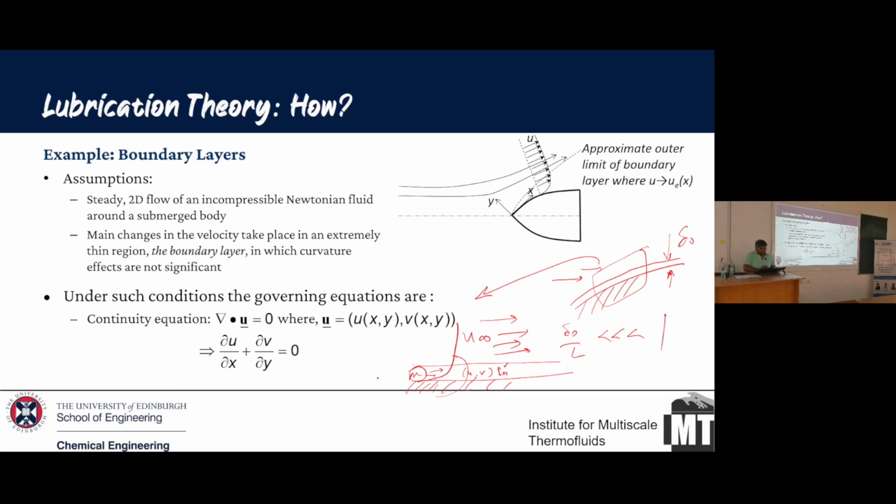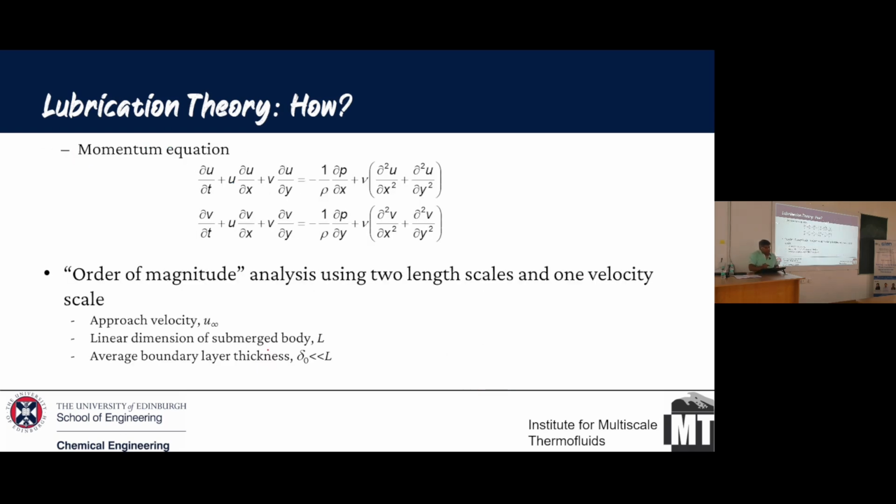Okay, so if you look at this, we have a simple continuity equation: del u by del x plus del v by del y. Now, because it's a 2D system, we can have a 2D momentum equation as well. Okay, so this is your boundary layer. This is my y-axis. This is my x-axis, and u and v are in action over here. This is how your velocity profile looks. And because it's such a thin film, we are not even considering gravity; the effective gravity is almost 0. Okay? So we don't have a rho g term here.